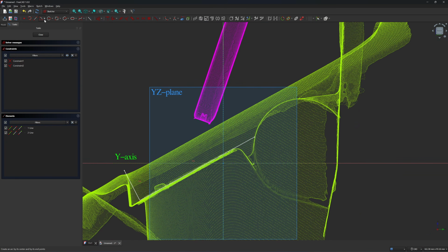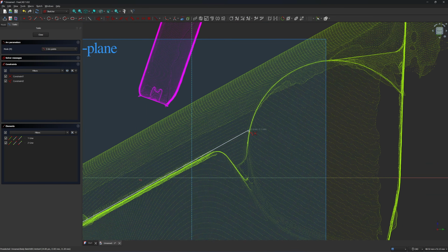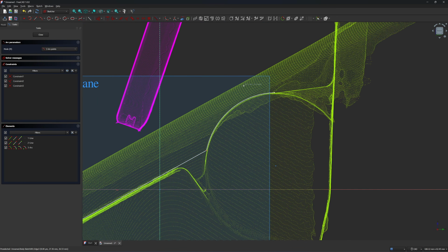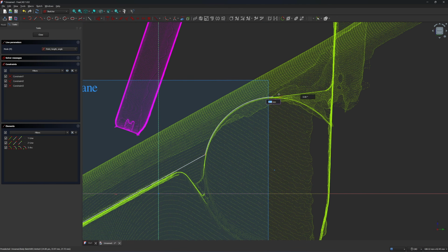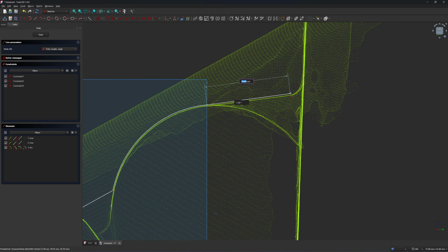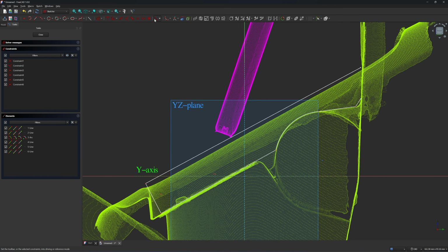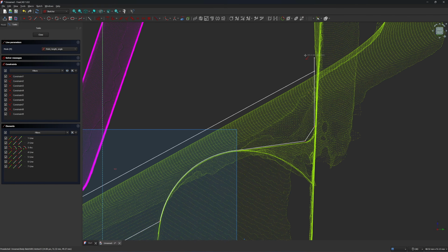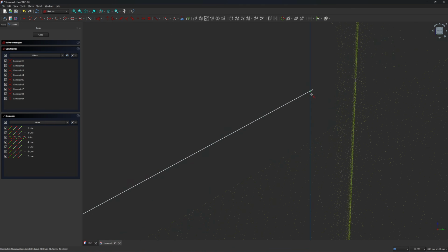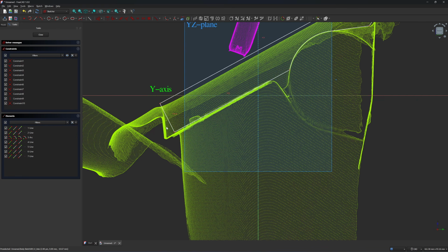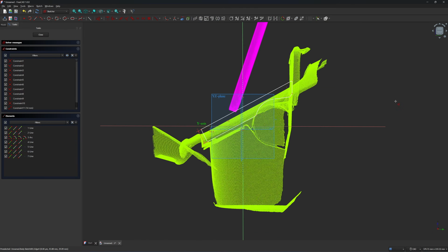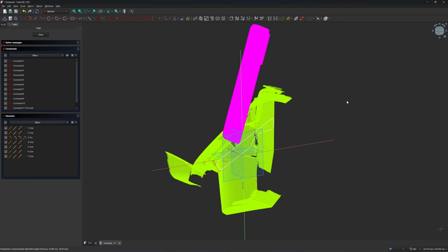Okay, next I'm going to use 3 line arcs, 1, 2, and 3. Okay, next I'm going to create a plane here. Okay, go up here, and I'm going up here. Next I'm going to create the line from here to here, and this line would be perpendicular to this line, so it's a box here to here. Let me trim it, trim edge. Okay, now I trim it. Let's put in a dimension, 14 millimeters. Okay, now we have our plane in the center like so.